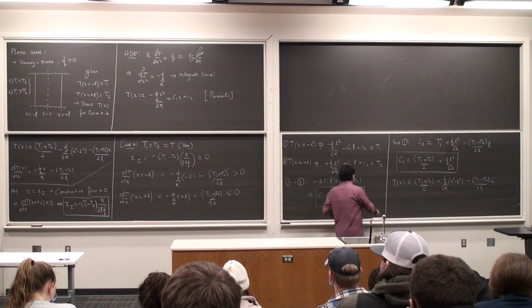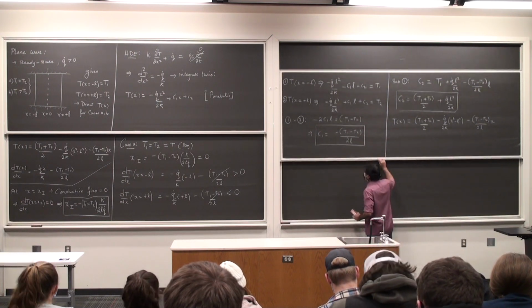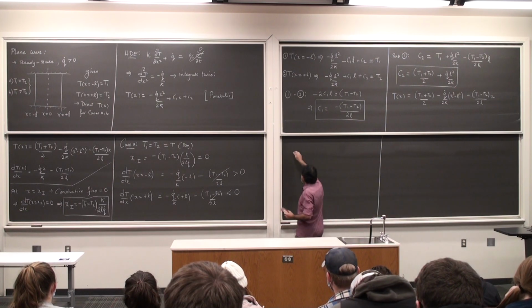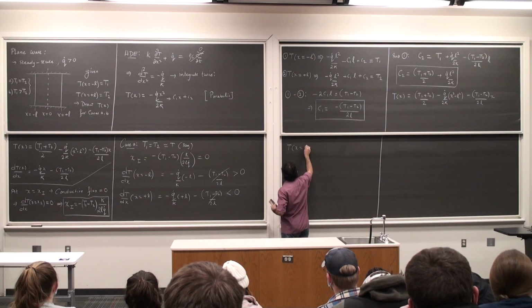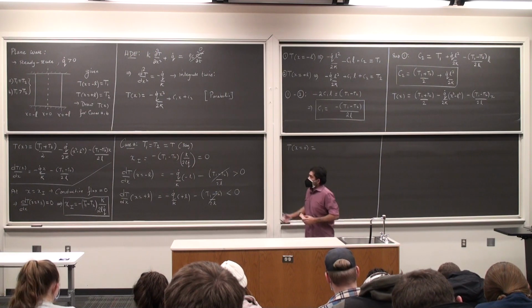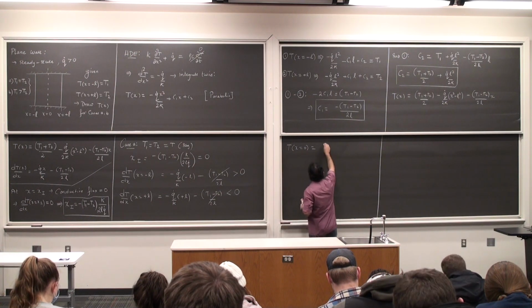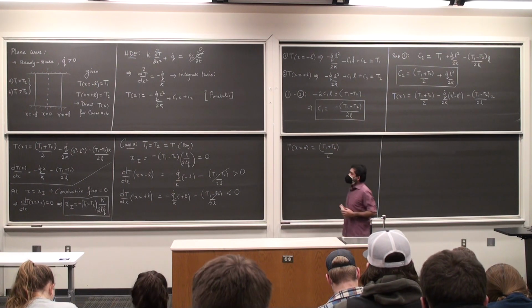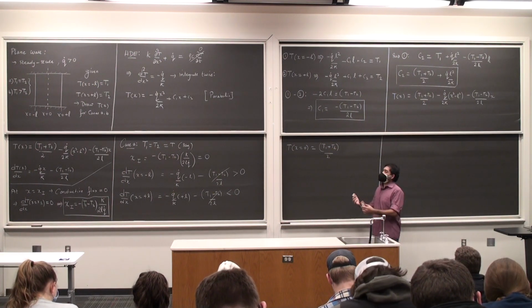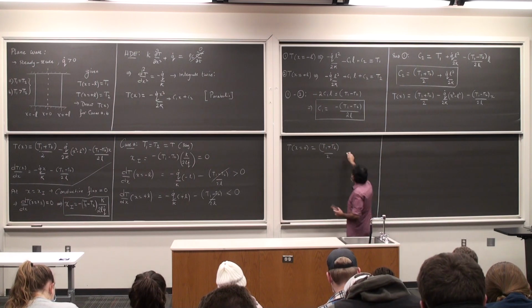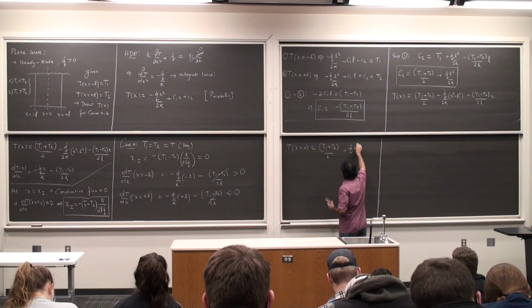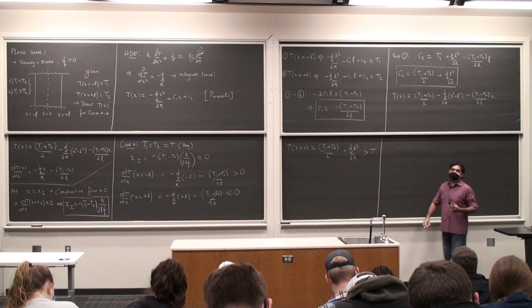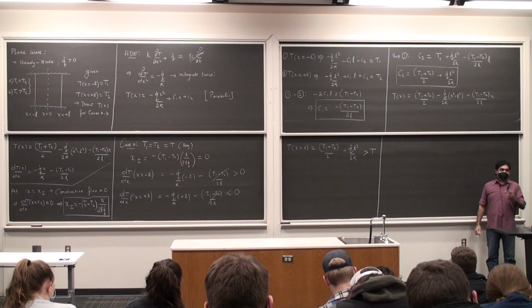Let's draw the profile. And if you want, you can figure out by asking, what is the temperature at x equal to 0? When x is equal to 0, I have (T1 plus T2) divided by 2 minus Q dot by 2K times (0 minus L) squared, or plus Q dot L squared by 2K, which is obviously greater than the temperature T of the walls.